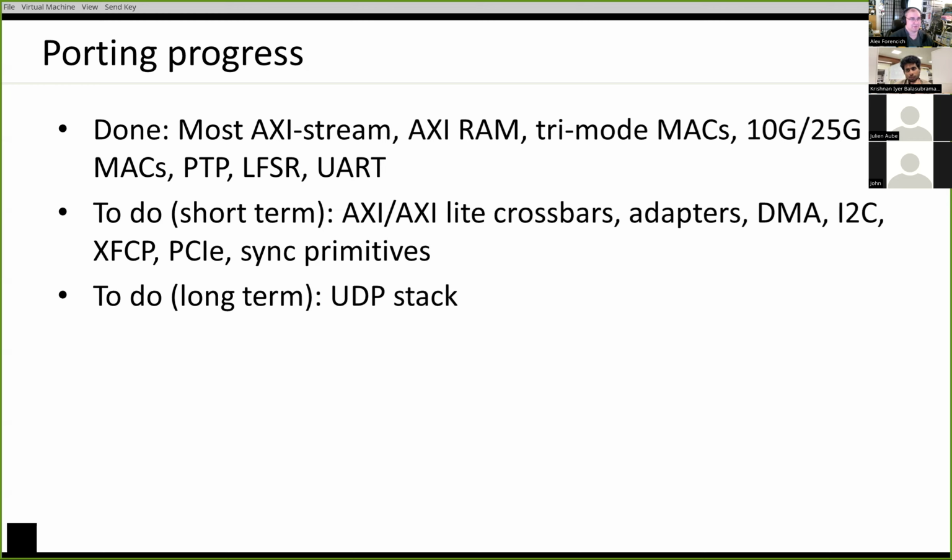Part of the reason for that was the limitations of Verilog, where you can't pass around multi-dimensional arrays, but with SystemVerilog you can. So I was able to rework and simplify it. Now it simulates better, and it doesn't take nearly as long to compile, which is nice.